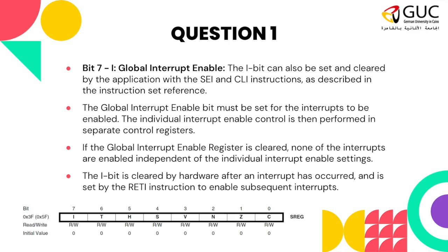My microcontroller will stop executing the program it was executing and will then go to operate on a certain method or function and return back. While it is operating on a specific method or function of interrupt X, interrupt Y cannot interrupt the functionality or operation of interrupt X. Interrupts can only interrupt the main program. They cannot interrupt each other. I cannot have an interrupt interrupting another interrupt.